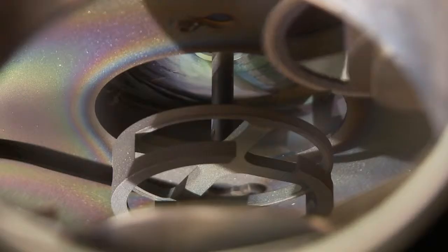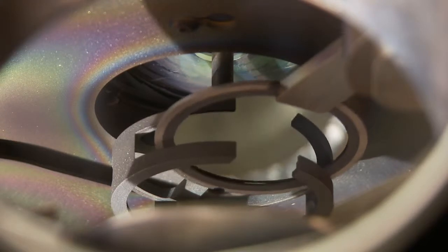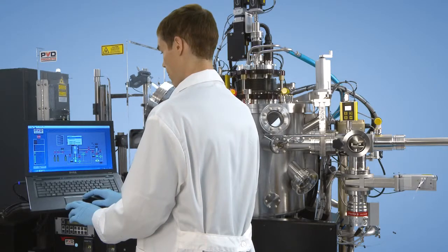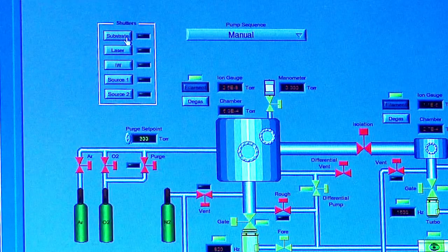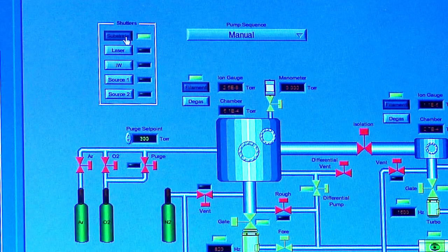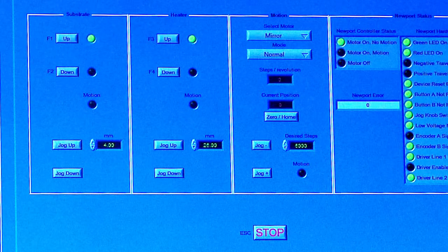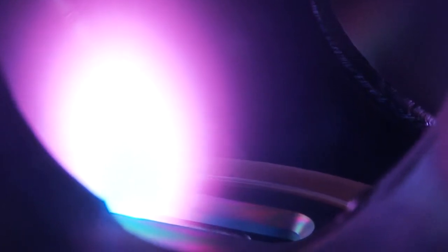The PLD MBE line of systems normally includes all pneumatic valves with closed-loop pressure control and auto-pump vent sequences. Our easy-to-use software interface allows the user to set up the growth of multi-layers using PLD and the other optional sources as required in a single recipe format. Data logging of all relevant parameters is also provided.